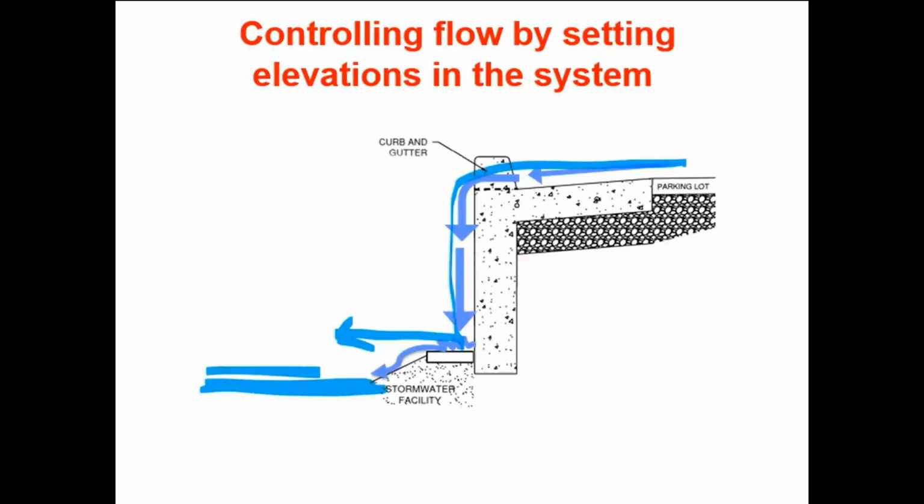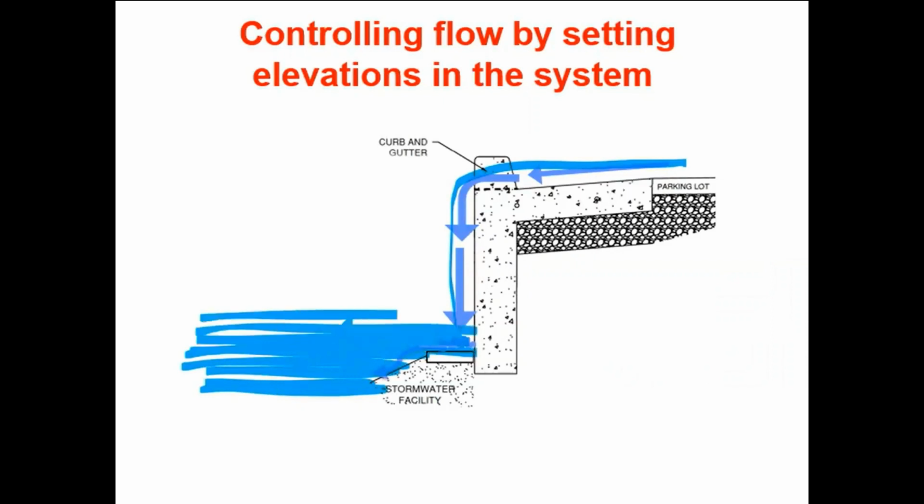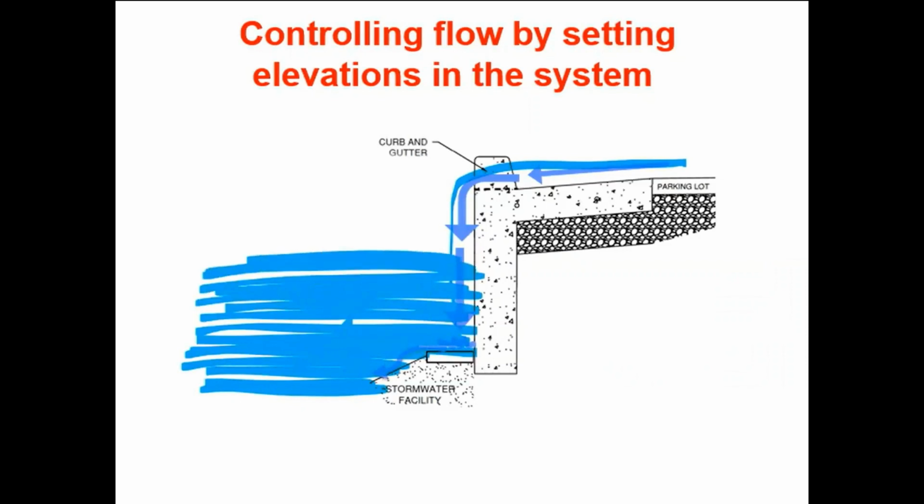And of course, it's going to slowly fill this area up. And even though we have the splash block down here, it could fill up much further if you wish. You can have that water fill up almost as far as you want. The difficulty is in what is a safe depth to have for that water. We're going to advise that you keep it at 1 foot or less for this assignment.